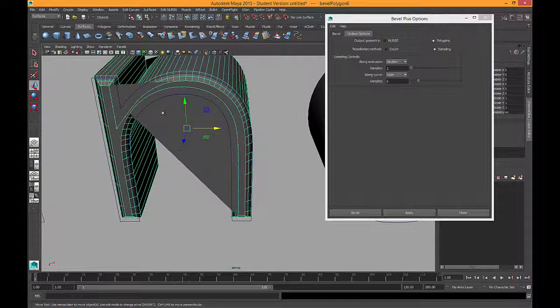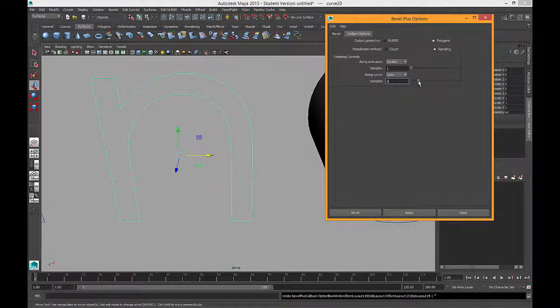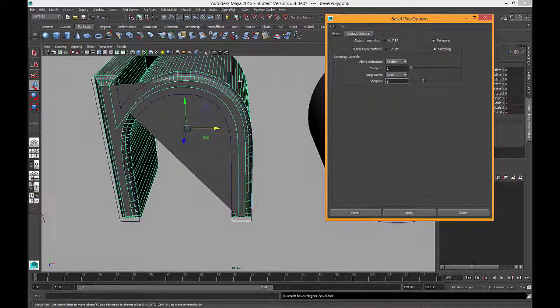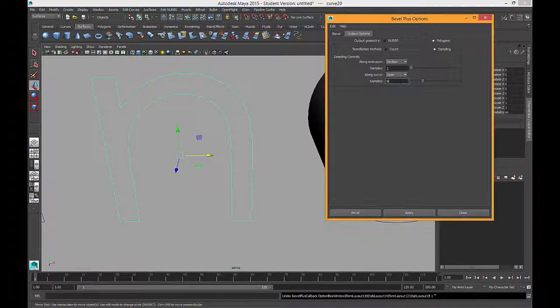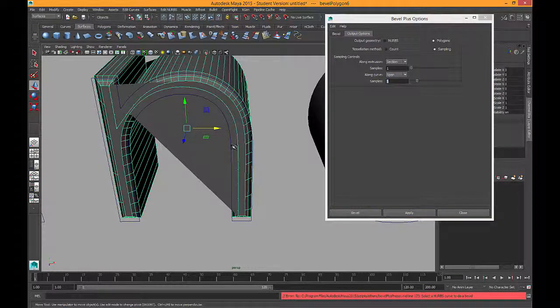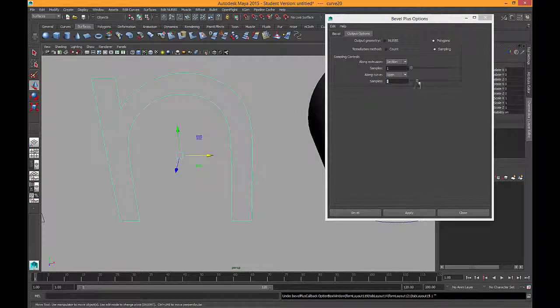So that might actually be a case of the span samples needing to be adjusted. So if I go up to maybe 9 and apply that, you can see that's still happening. We can maybe drop it down to 5. All right, you basically got to go back and forth until you're happy with it. So let's drop it even lower.